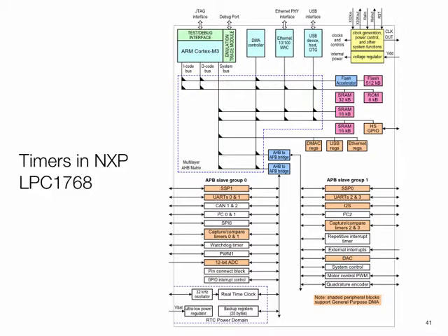And the two disks which we have of this nature, they are slightly phase shifted. So if one signal comes before the other, it means the motor is moving one direction. If it's in the reverse, it's moving in the other direction. So you basically get two signals which are both periodic, they are phase shifted, and the frequency tells us the speed, and phase shift tells us the direction. And that is very, very commonly available from motors and other similar equipment.